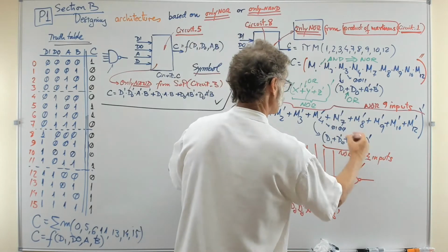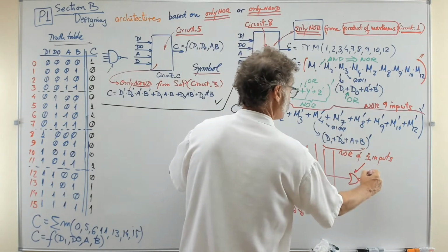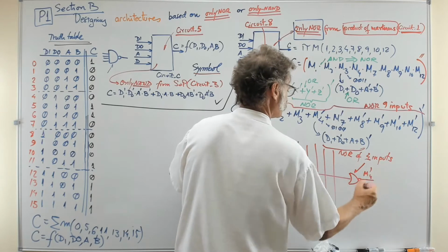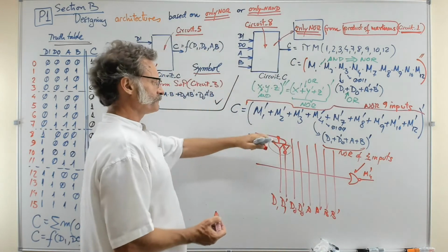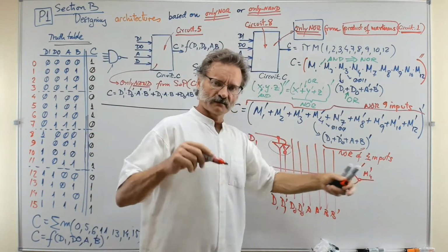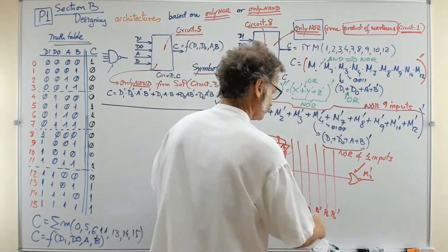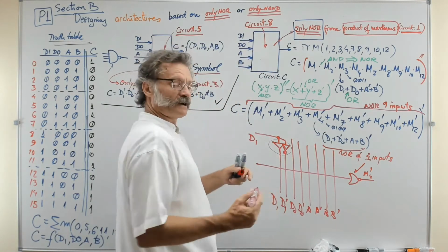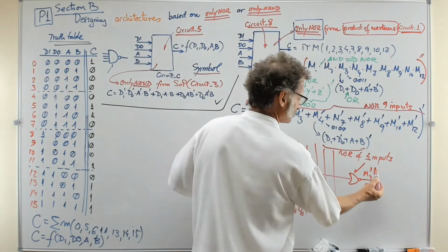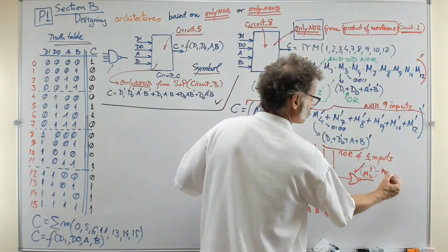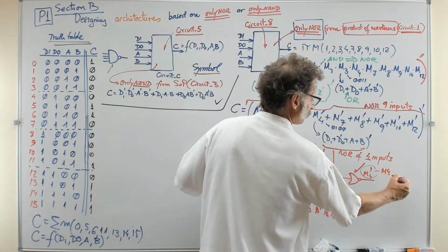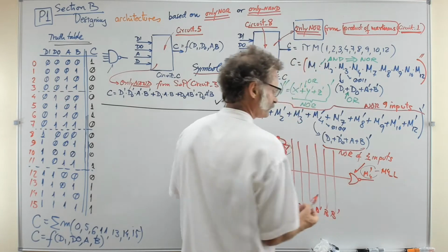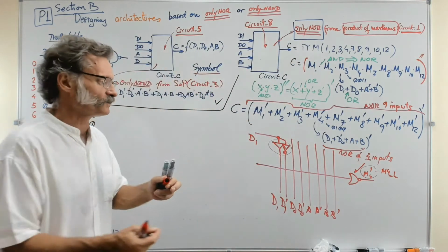So let's do that one. For example, this is going to be the M4 NOT, right? You can name them this way. If you have a wire, you can name it like this, for example. Or if you have to write that in VHDL, that is inconvenient. So in VHDL, this may be named M4_L. If you have to give that wire a name, you can use this.